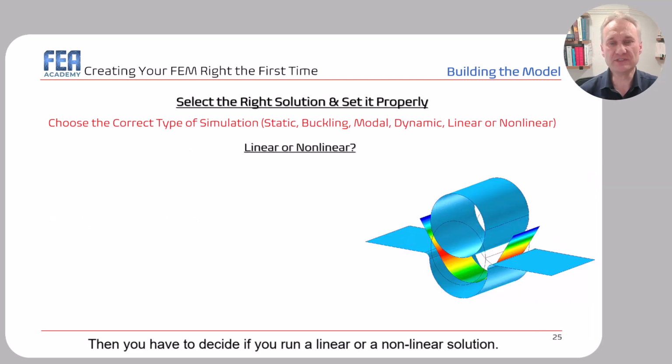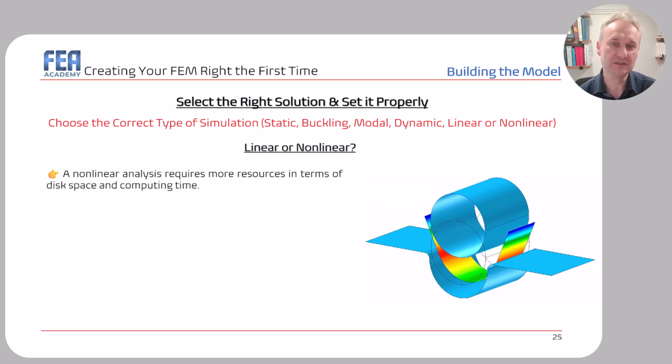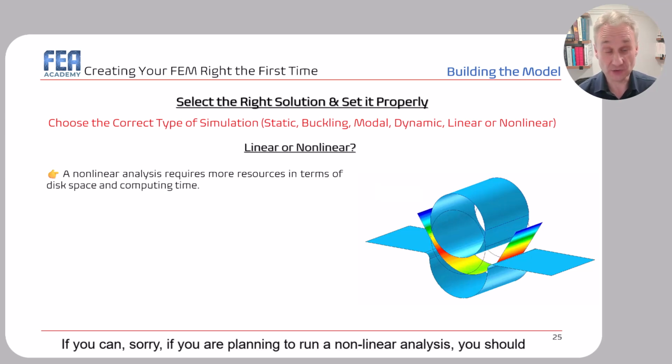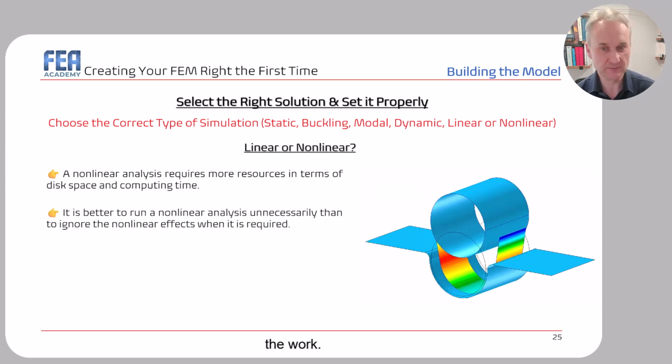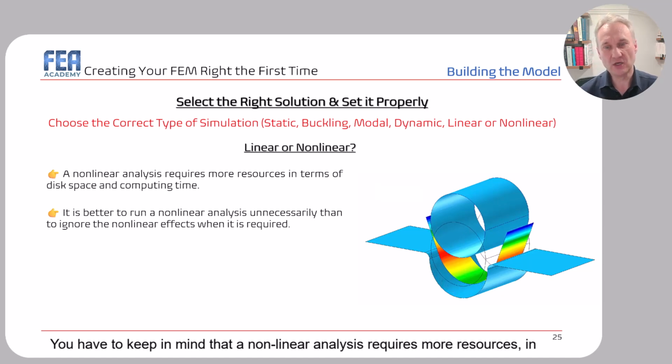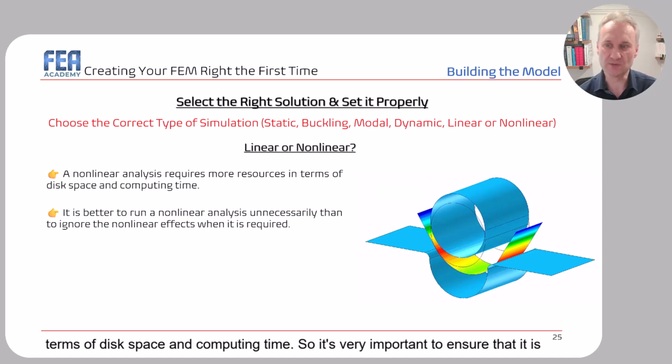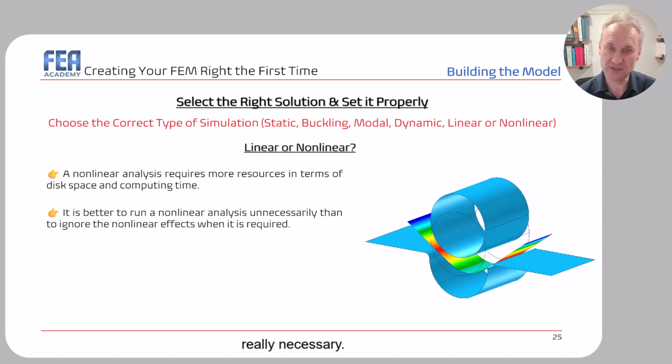Then you have to decide if you run a linear or a nonlinear solution. If you are planning to run a nonlinear analysis, you should answer a few questions to decide if you really need to or if a linear analysis will do the work. You have to keep in mind that a nonlinear analysis requires more resources in terms of disk space and computing time. So it's very important to ensure that it is really necessary.